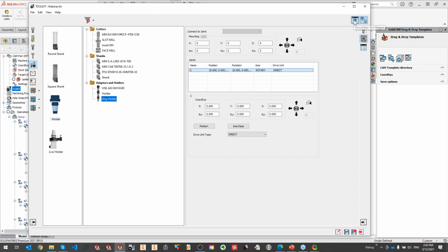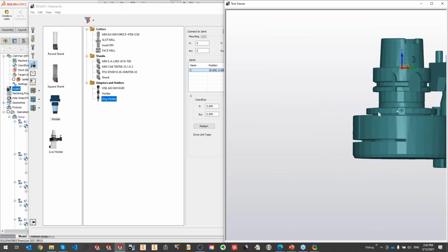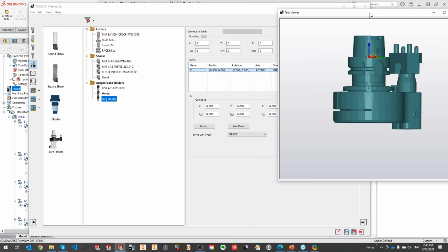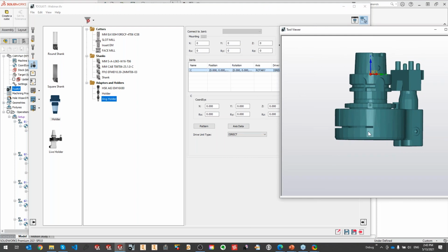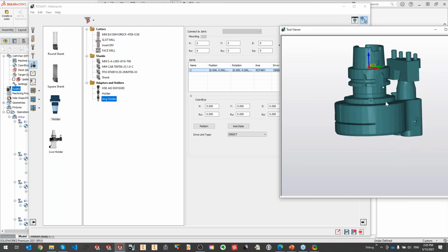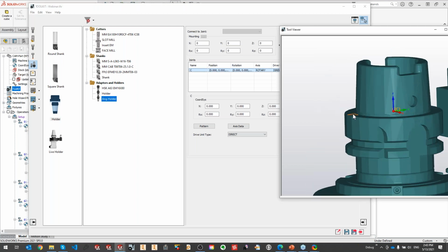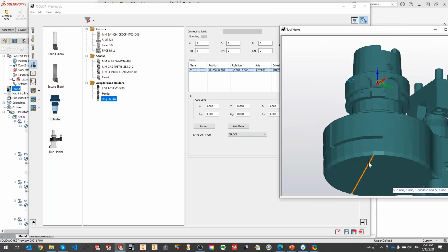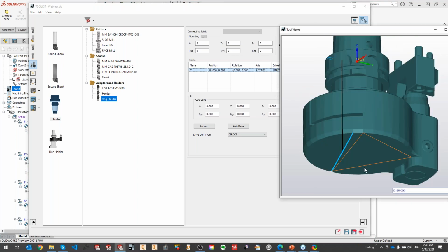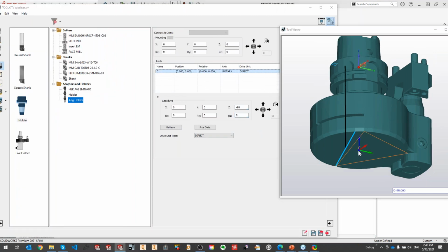Let me go to the show hide picture. Great. Doesn't look anything so special. The only thing we need to do is shift this over here, exactly in the middle. So how to do that properly? Again, you can use the measurement. You just click over here, hold the control key, click on any entities here. We have like 98. So I'll just put here minus 98. And here it is.